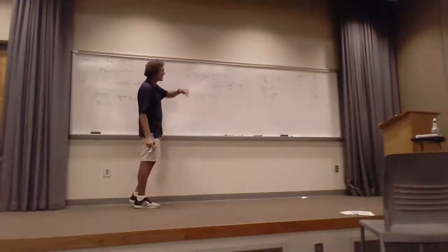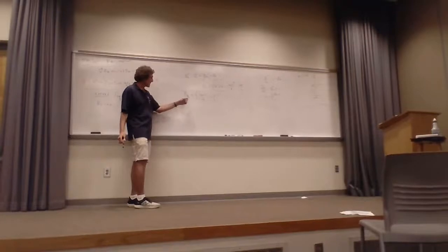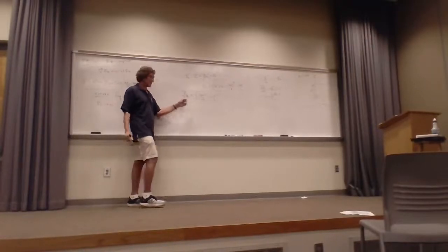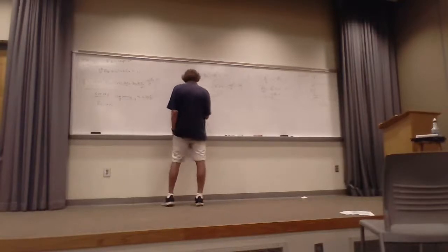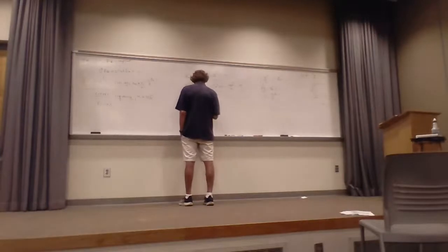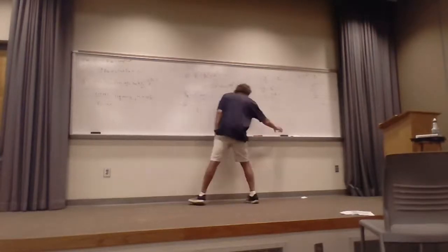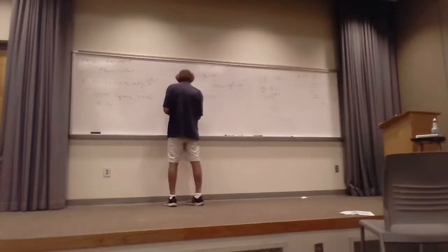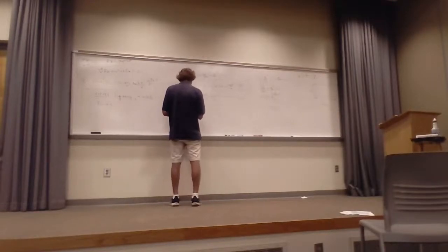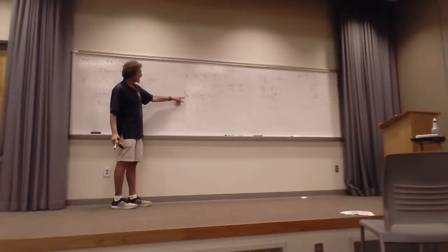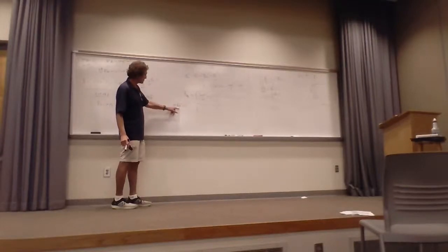I've taken this equation, got rid of beta z because I'm looking for the cutoff frequency. That's what beta unguided is, right? The cutoff. And beta unguided is equal to omega cutoff, the cutoff frequency, and omega times the square root of mu epsilon is equal to this mess. I'm going to do one thing here. So beta unguided right there is equal to omega squared mu epsilon right there.